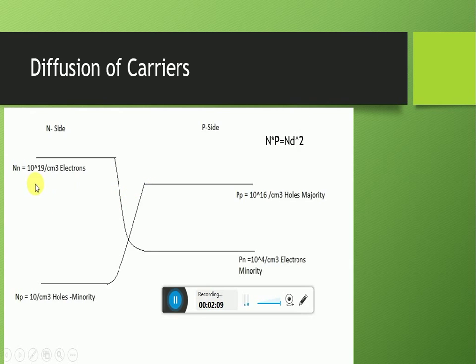The lifetime of these carriers is also very important, and the open circuit voltage also plays a very important role because that is dependent on the lifetime of these carriers. Minority carrier diffusion lengths should be higher than the thickness of that material so that they can reach the surface or the junction, and the surface recombination velocities must also be kept very low.